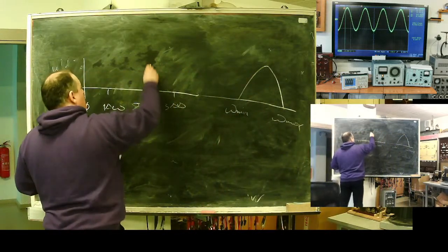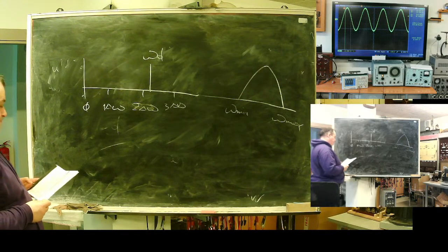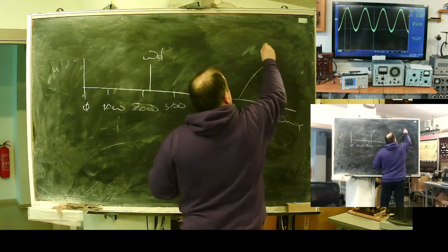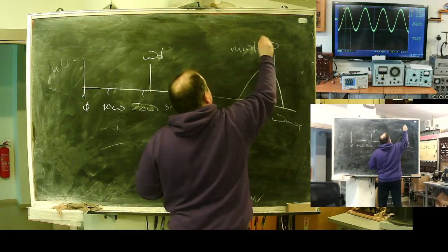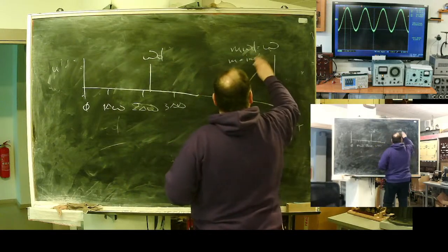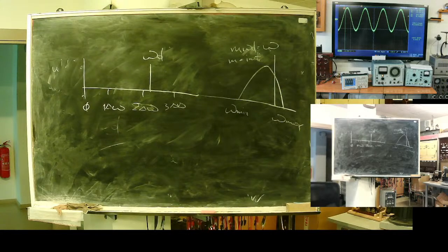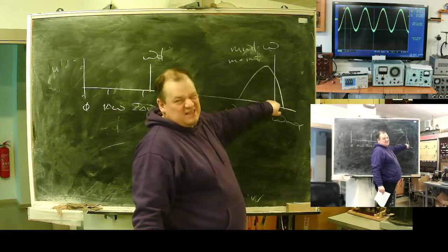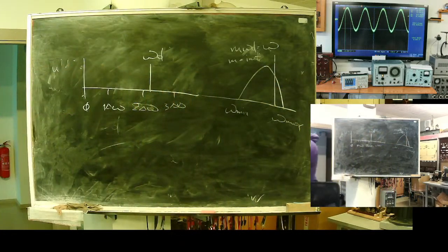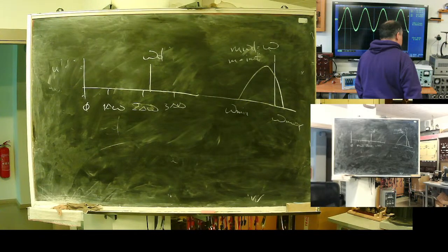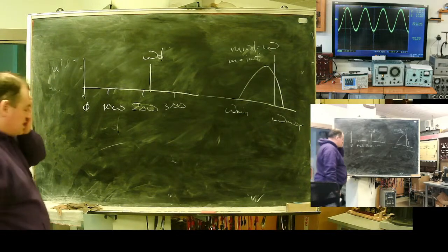But if you take omega discretization above 2 delta omega, you will have this strange omega being m omega d, where m is an integer. And the problem: this part from the whole spectrum, this part and around it, because we need to deal with real tolerances, will disappear from the result. In such a case, this means part of your signal spectrum is lost.